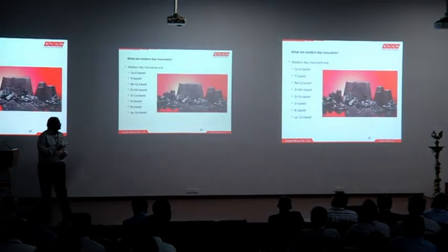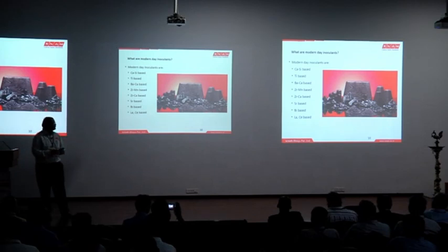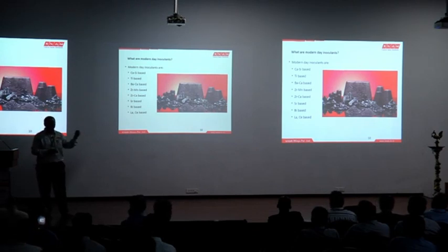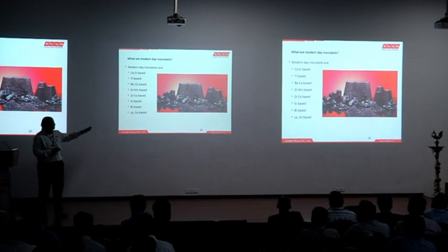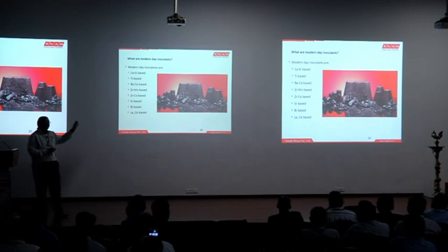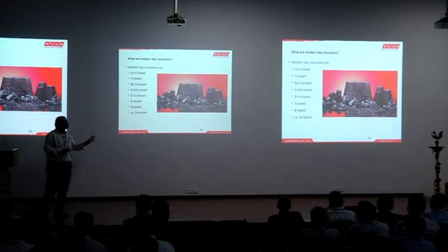So these are different modern day inoculants available. These are different elemental combinations, either individually or in combination with other elements, being used in today's foundry industry to manufacture the thinnest to the thickest castings available today. And all of these are ferrosilicon based. So these are the varieties available, and you may add iron silicon to it. Iron silicon may be contributing 60 to 70% of the total weight by weight, and the balance will be these elements.